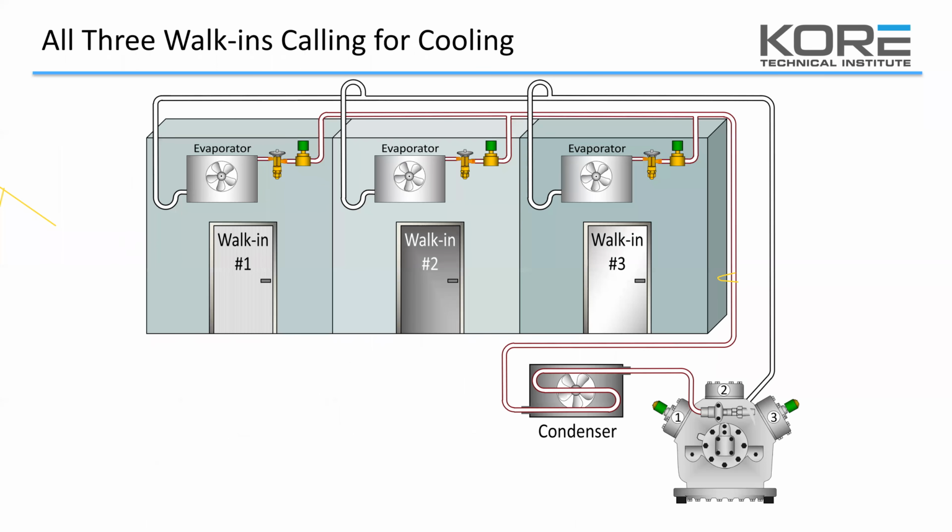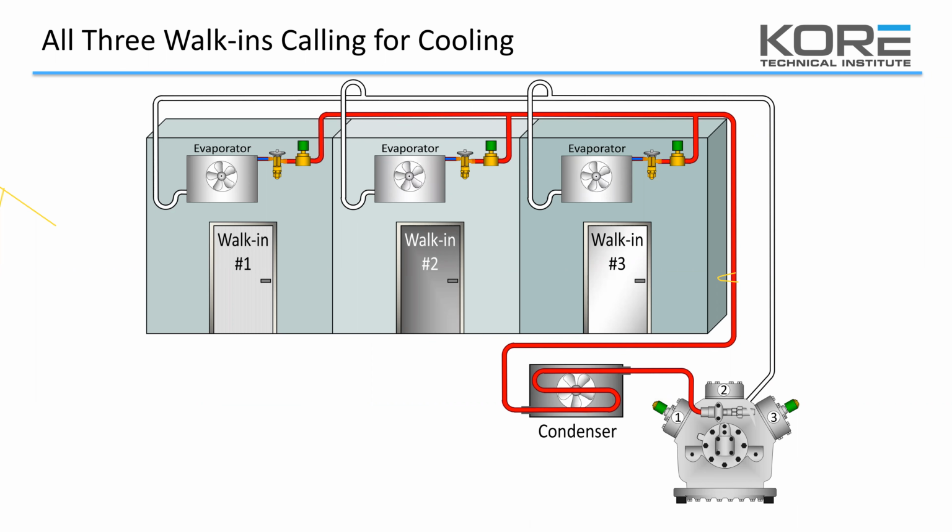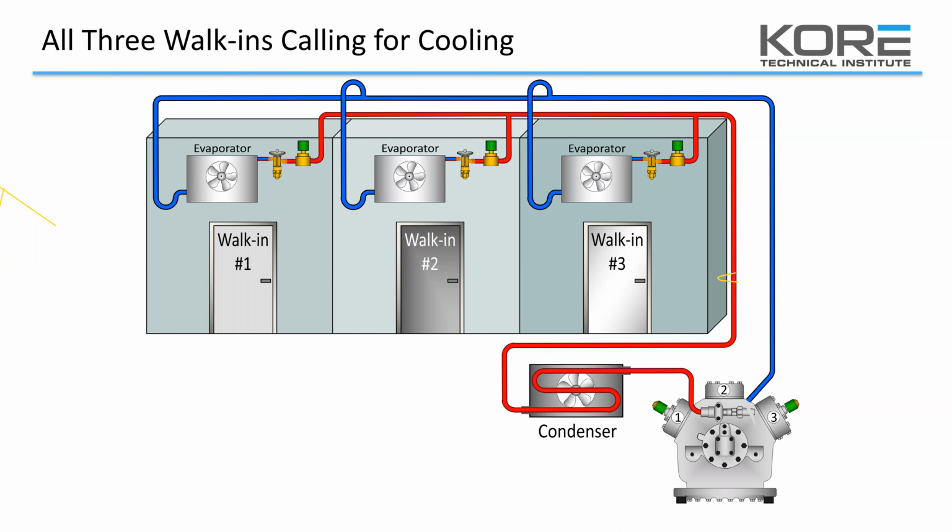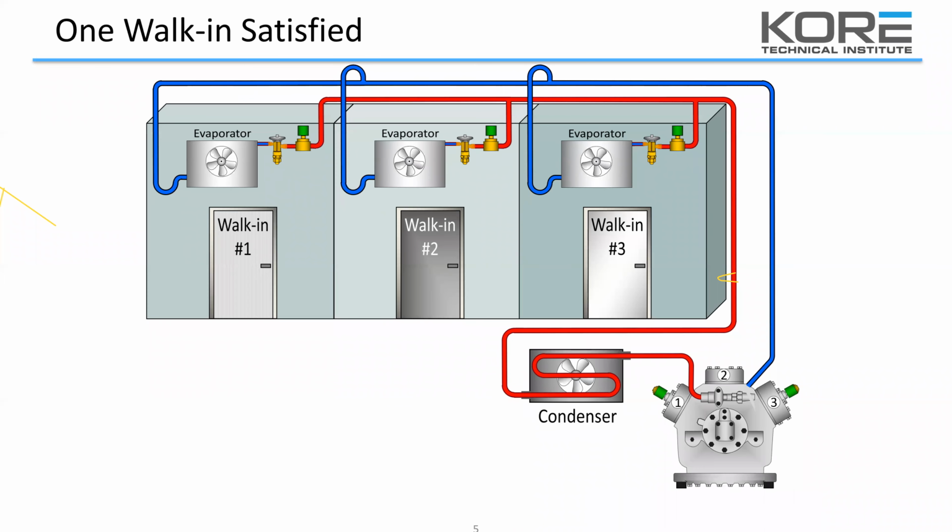So here we'll see we got 3 evaporator rooms and 1 compressor going through the condenser, and this is operating at full capacity. We watch the little discharge gas flow up and feed all 3 liquid line solenoids. Suction is going to come out from all 3 evaporators, return back to the compressor. So that's under full load. The compressor is running its matched CFM for keeping all 3 evaporators satisfied, full of refrigerant, and everything good. So all the cylinders are loaded, everything's going according to plan.